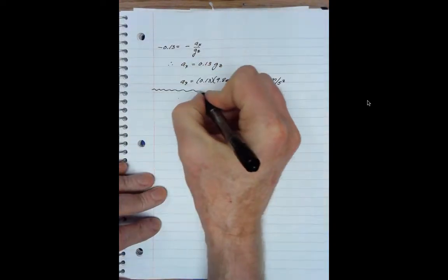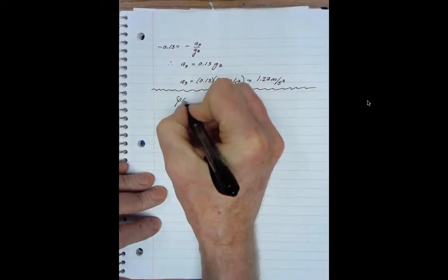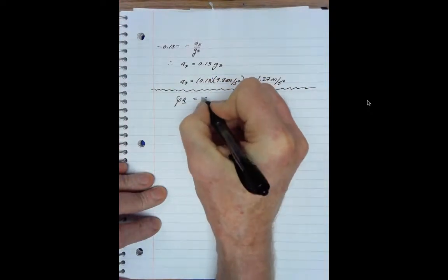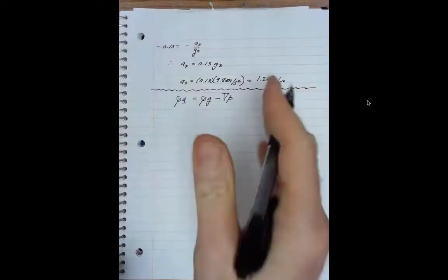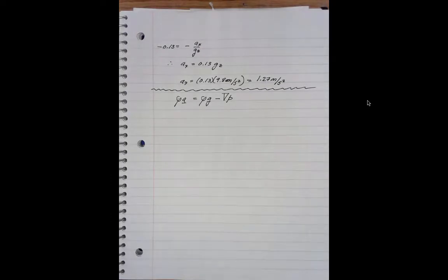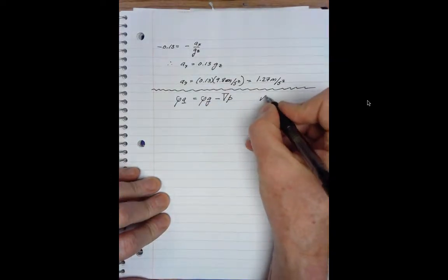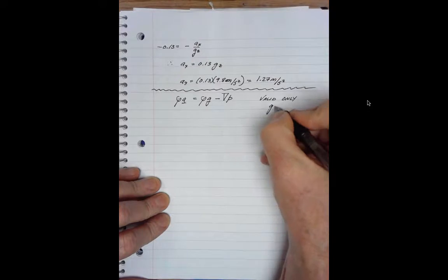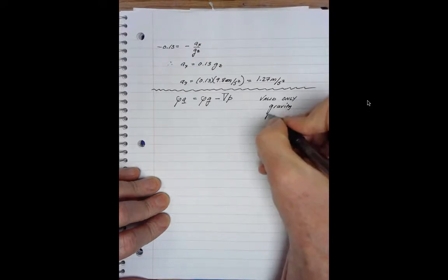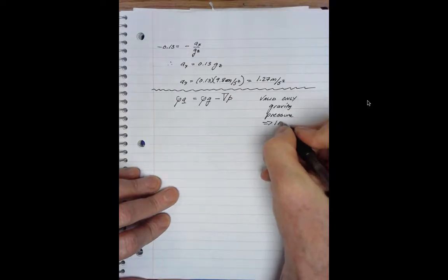So Euler's equation of motion for a fluid is mass times acceleration equals gravitational minus the gradient of p. I've just rewritten it, but I put the acceleration on the left. It's valid only when the only forces are gravity and pressure, hence inviscid flow.